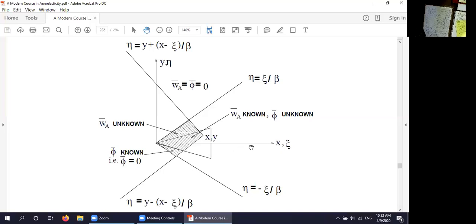And also it means once I create a disturbance back here in the wake behind the wing, it's also moving with the speed of sound. And if this is flying at less than the speed of sound, then this disturbance can catch up to the wing. So I disturb it back here, but then that disturbance moves through the fluid and catches up with the wing. So what does that mean? That means that I cannot consider just a limited area of disturbed flow, as in the supersonic case.